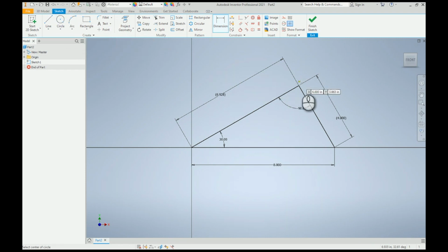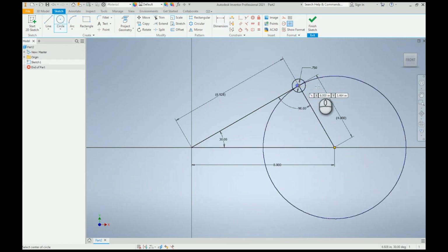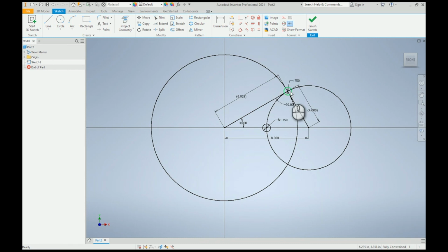Let's draw now the driving pin. For diameter we can do 3/4 of an inch, just a proportional dimension, without any calculation for this example. This is the circle that the pin will travel. By putting a pin here, we can see how close it gets to the center of the Geneva wheel when it rotates. This is the outer diameter of the Geneva wheel. If we transfer this radial dimension, we can determine the bottom of the slot.